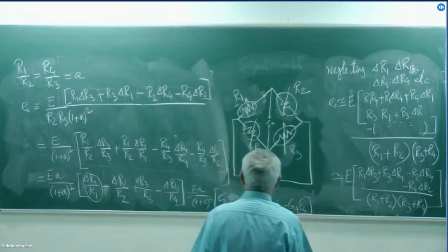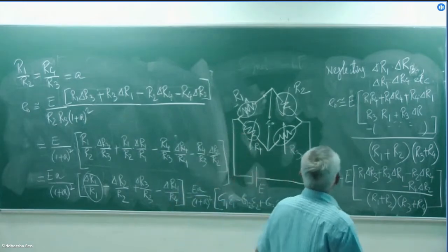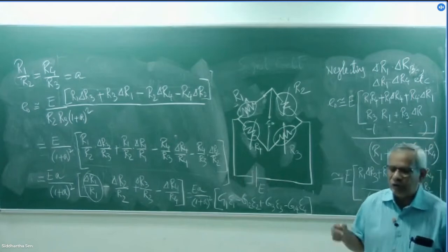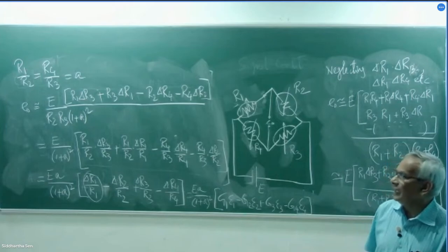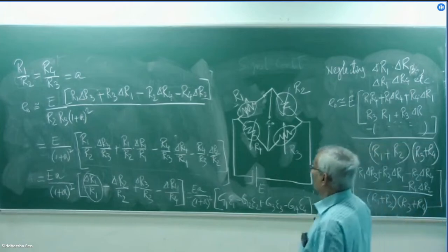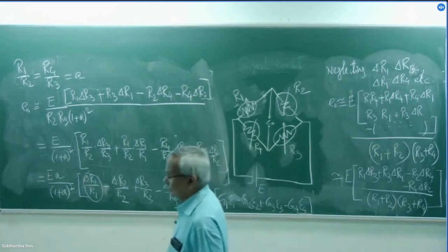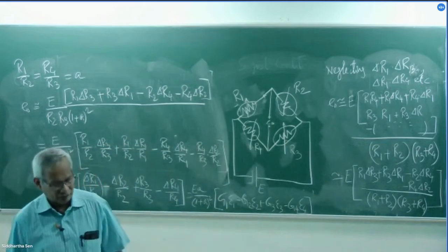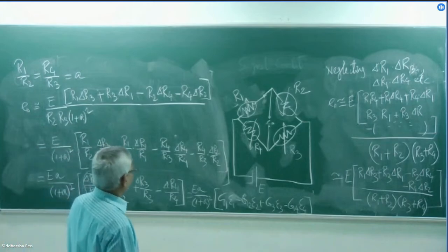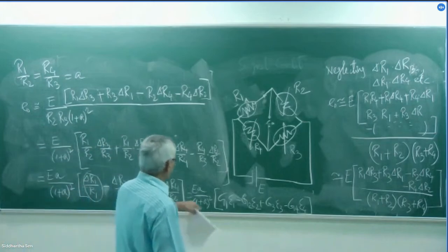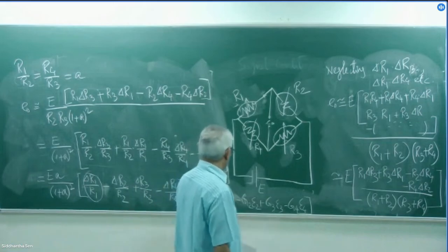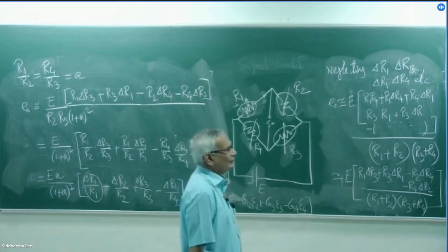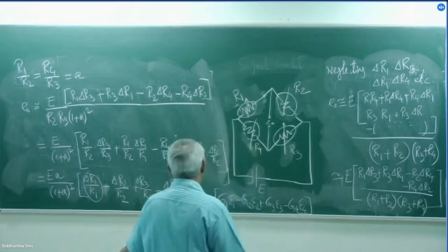So it's a very nice expression in the way that it is the most general expression, that even though all the strain gauges are of different gauge factor, and all the strain gauges are experiencing different strains also, if we know the G1 and epsilon, what would be the value of the unbalanced voltage? I can easily calculate and find out there.